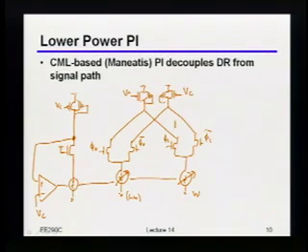If your VC goes down, your resistance decreases, but you have more voltage drop, doesn't that mean a lot of current? That means that I'm increasing the current. But by the way, that's exactly what I need to do, because remember that when I lower the resistance, I'm trying to increase the frequency. So if you just think of it from a CV squared F standpoint, that's kind of the same thing that I'm trying to do here, just in the analog domain. It's not the same thing as your PLL anymore. Yeah, there we go. It's really annoying, right?